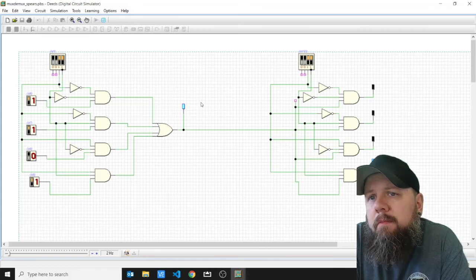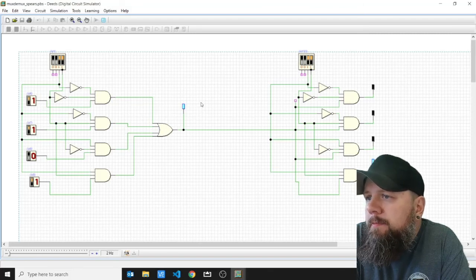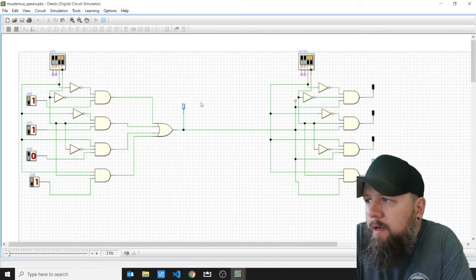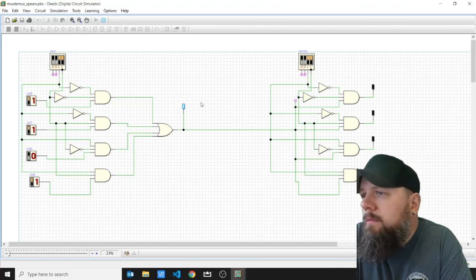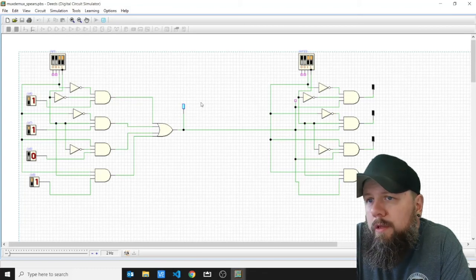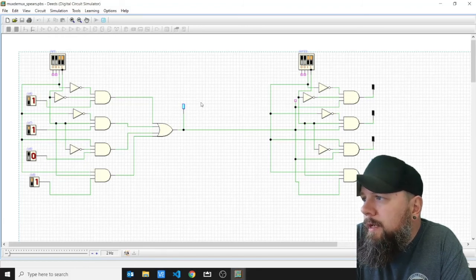This is kind of the basis of what we use for serial to parallel and parallel to serial also. All right, so serial to parallel, we would clock in bits one at a time, load them up so that they're side by side, right? And then put that out. And the opposite for parallel to serial would load up, let's say 4 bits, and then we'd clock them out one at a time. Okay.